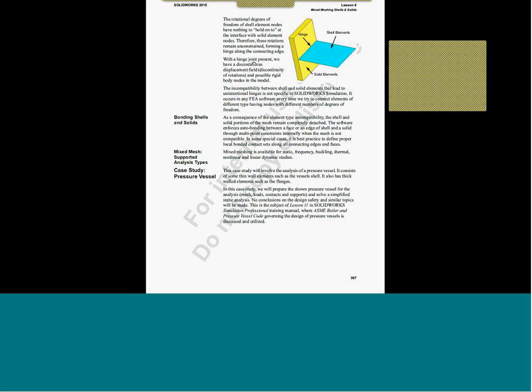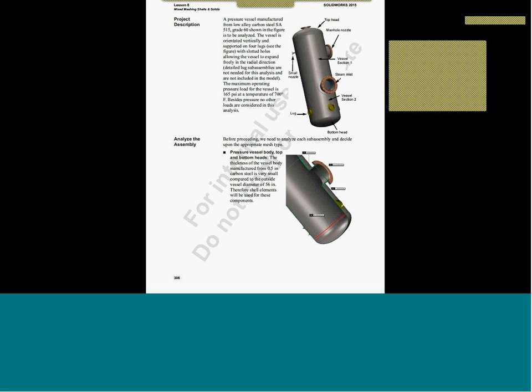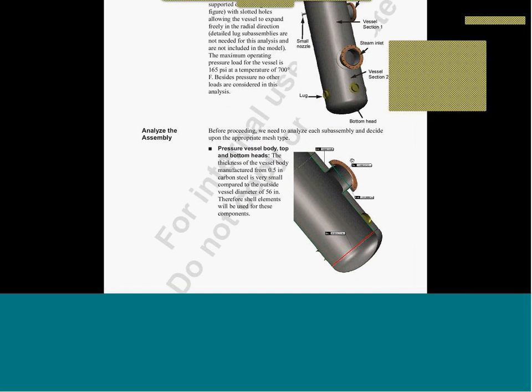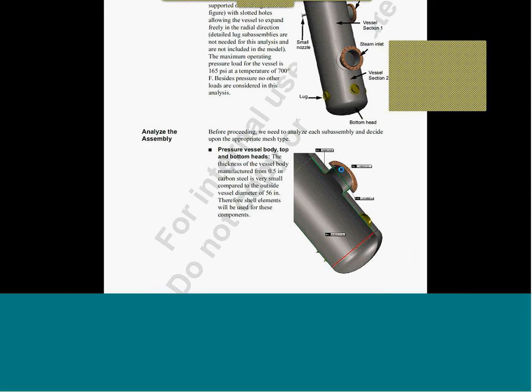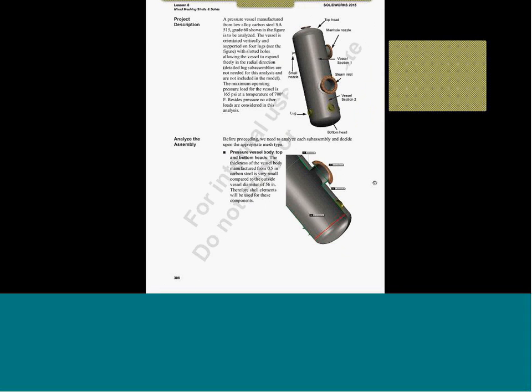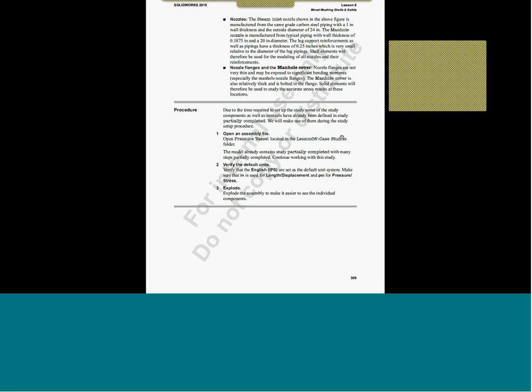This is an example of a pressure vessel and joints, especially what you are seeing here. These are the brown part over here. Unfortunately, because of the overall dimensions, and we want to simulate the bolts accurately as well, we may not be able to simulate it as shell elements. In such cases, we end up mixing solids and shells, and in these cases, we need to be aware of what happens, how it goes, etc.